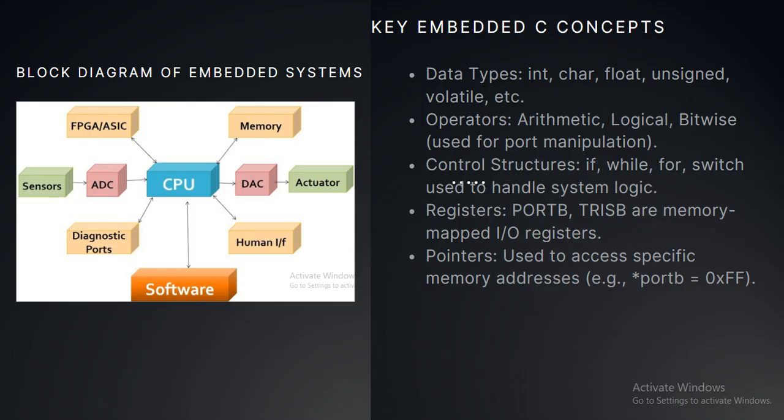Some core concepts I use include data types, bitwise operators, and control structures like if, while, and switch. I work directly with hardware registers like PORTB and TRISB to control outputs like LEDs. And then pointers are also used to access specific memory locations. You can see on the left side corner the block diagram of embedded systems.